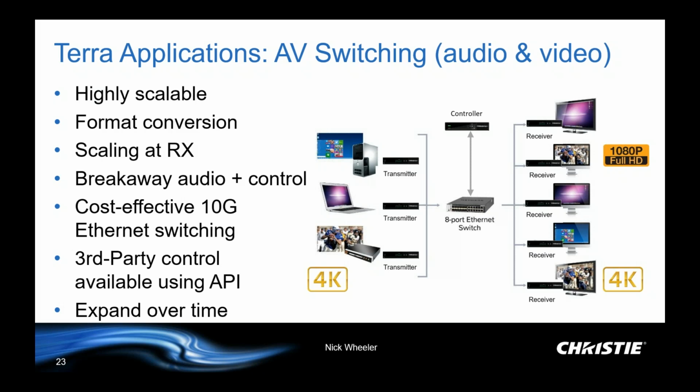If you do the same thing with SDVoE over a network, then all you do is just add a switch to your design, to your installation, and you're adding more ports. And the ports can be inputs or outputs, and they can change as well. They don't necessarily need to stay inputs or outputs. So the whole thing is scalable and modular. You can change things around very, very easily. A port is pretty dumb, as it were, so it can be whatever you want it to be at any one time. So it's incredibly flexible.